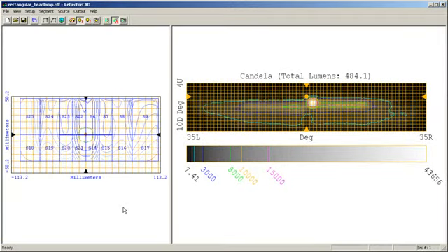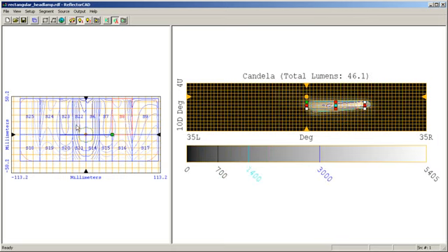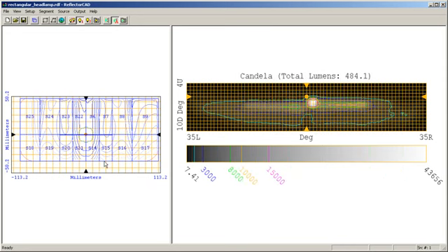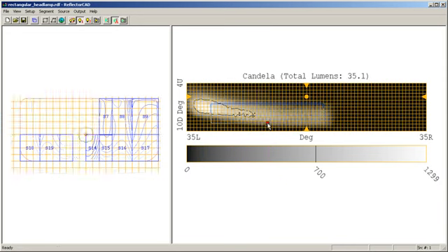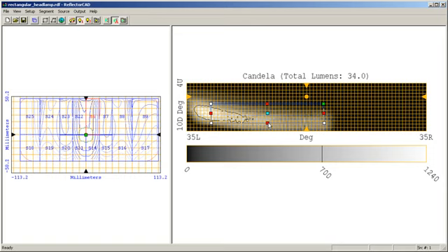ReflectorCAD was developed as a new design paradigm and packaged as a true graphical user interface to provide a long-needed illumination first-order design tool for segment reflectors. ReflectorCAD allows you to graphically lay out the reflector segments, to compute very quickly the approximate intensity from individual segments or all of the segments in a source, and most importantly, to graphically adjust the radiometric output from each individual segment. ReflectorCAD then automatically will adjust and create that segment corresponding to that particular radiometric output.